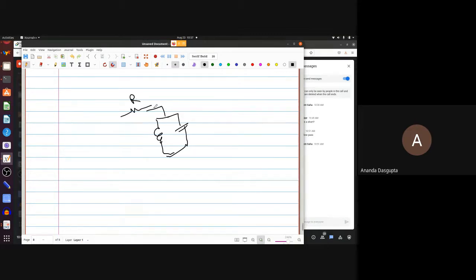Pardon my poor drawing skills, but I was just wondering, what would you call a circuit where all L, C, R are in parallel? Because when I first read parallel resonant circuit, I thought all of them are in parallel. The trouble with putting all three in parallel, that's a good question, is that a resonant circuit is meant to produce a huge output at a particular frequency and very low output for other frequencies, right?